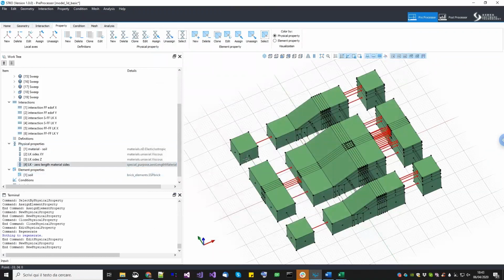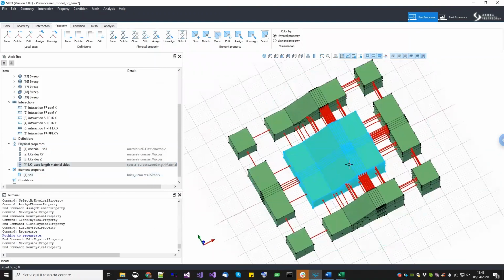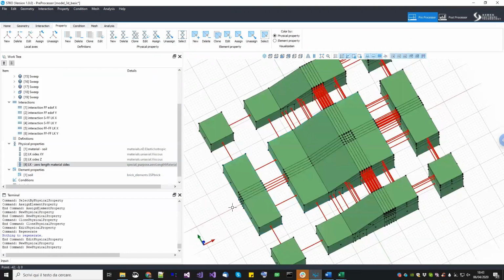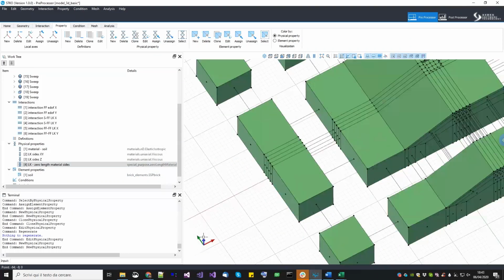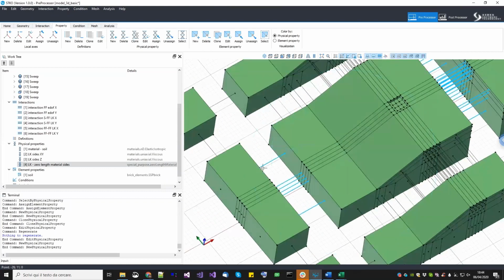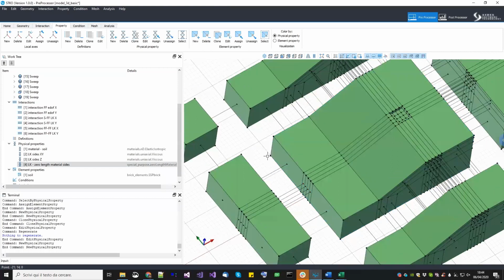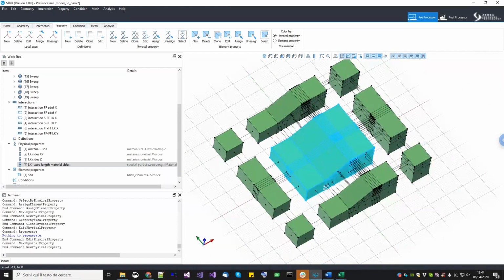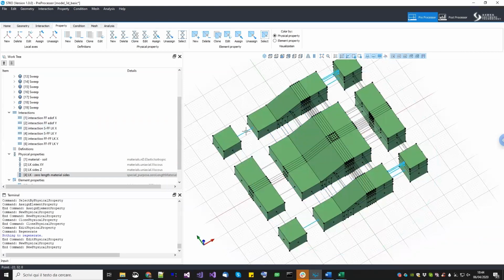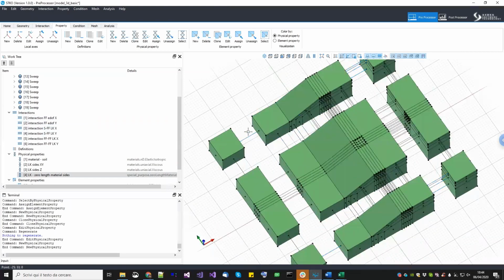But then we have a problem. As you know very well, in OpenSees, the zero-length element does not have a physical geometry. So by default, its orientation is the same as the global axis. And as you can see, the global Z axis is pointing upward, while instead we want the Z axis to point along the line. This is not done automatically, but in STKO, we have a way to assign local orientation to zero lengths.